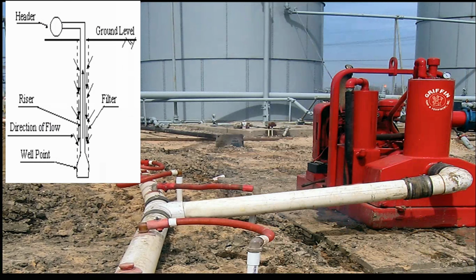Now, when we utilize any of the methods, the actual scenario looks like this in the cross section view. So this is your well point. It is used with the suction method. Then after the water is collected by it, it goes in this one direction, connected with the header pipe and the pump, and from the pump via the discharge pipe. Okay, so the same thing is also seen like this.